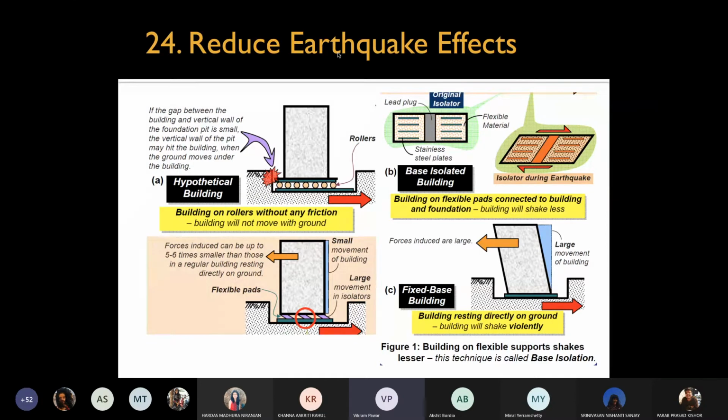So for the performance of such buildings, if there is vulnerability, you have to think about them as a last resort. For such buildings, it is important to remain functional, and not just be able to absorb the shocks and remain standing, but remain functional even after the earthquake. So it is important to introduce devices which will help in making them more flexible, so that the earthquake does not affect the building itself.